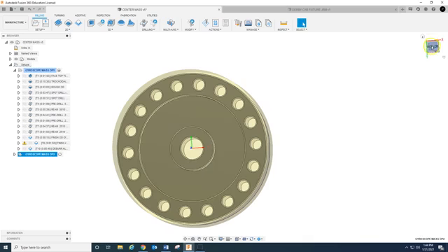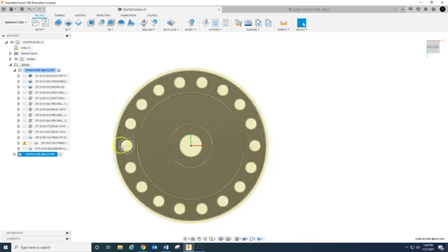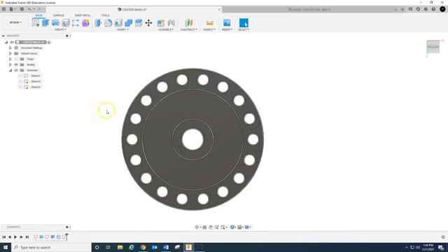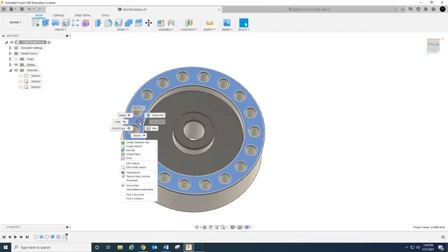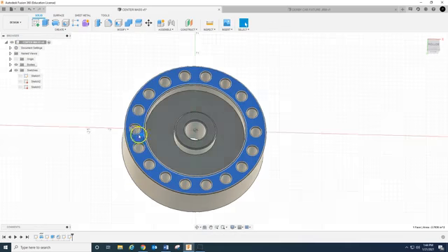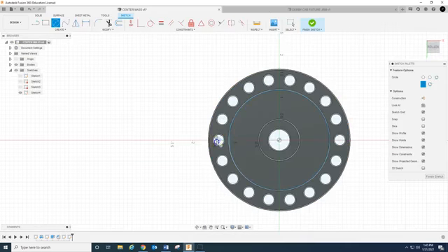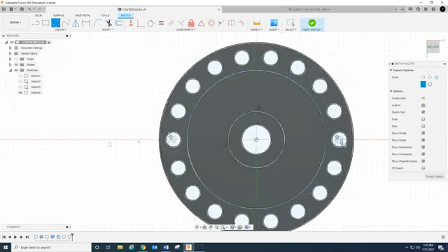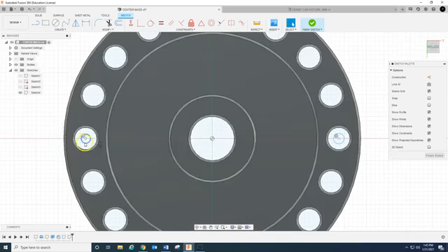And the plan for this is, being that we've got these 2 holes that are all the way through, you'll be able to put dowel pins in this hole and this hole, and you'll be able to put a parallel across. And tell you what, let me show you a bit better over here. So you're going to put a dowel pin here, dowel pin here. Let me make these the same.